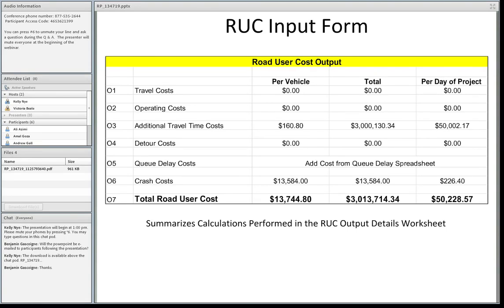It is important to note that when running the analysis, if you are going to be changing different types of scenarios, so changing your lane closures, changing your speed limits, this is a scenario-based tool only, so you would have to run a second scenario to capture that additional information. So if you know that you're only going to have 60 mile an hour speed limit in the construction work zone for 10 days, you would have to run that and then run it again for 70 miles an hour for the rest of the 55 days, for instance.